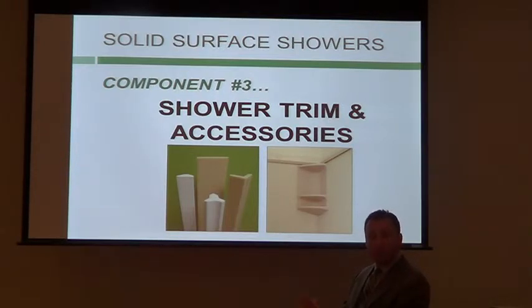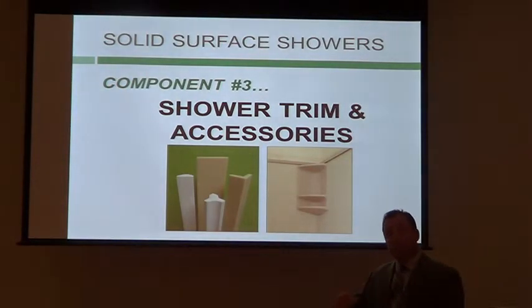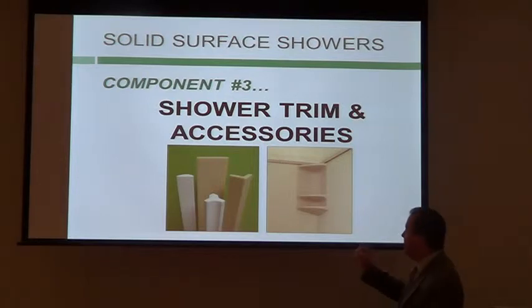Scribing the panels, doing a great job, even the best craftsman in the world only has about an 1/8 inch overlap where those two panels come together. And it's silicone. Great. Good enough? Maybe. But if not, add 2 additional layers of protection by adding silicone and an inside corner trim. Now you've got 3 layers of protection, and the only point it can be vulnerable to moisture. Everything else is non-porous. Okay?